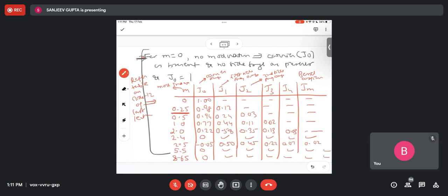Basically, what we see if you look at this table is the amplitude of the side frequencies. There are three values, which I have marked by this color, 1, 2, and 3, for which all power lies in the side bands and there is no power in the carrier.